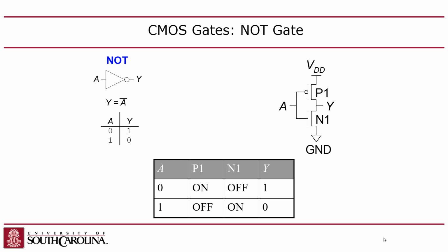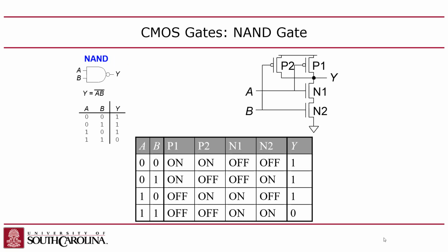So only either the PMOS at the top, you can think of it like PMOS positive, VDD, pull up. P is, think of it as positive voltage, right? NMOS, negative, ground, pulls down, right? So they're complementary, so only one of those guys is going to be on at a time. Make sense? Now, you can extend this pretty easily into more complex gates.